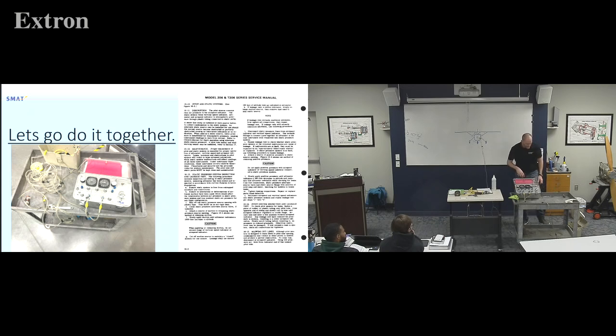And then basically what I would do, where'd the end of my hose go? Lost my piece. Basically what I would do is I would open, I'm going to make sure that's closed, cross feed is closed. I would open up until I get to 150 knots, right there, close it, and I'm going to wait, is it a minute? Use a minute, double check AC43. As long as it doesn't move, I don't have a leak in my system, right? Easy enough. If I have a leak in my system, it would move.